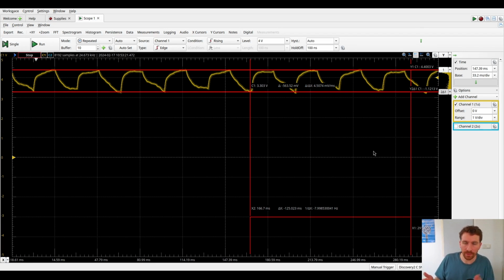We're putting 5 volts through the voltage divider, and we only actually have 1.21 volts of change that we can use to observe this. So the tricky thing about that is that we can't plug this into a microcontroller and expect to read this signal, at least not in a digital way where we could expect to see these as digital peaks, because we're actually just not going to detect the difference between the levels here.